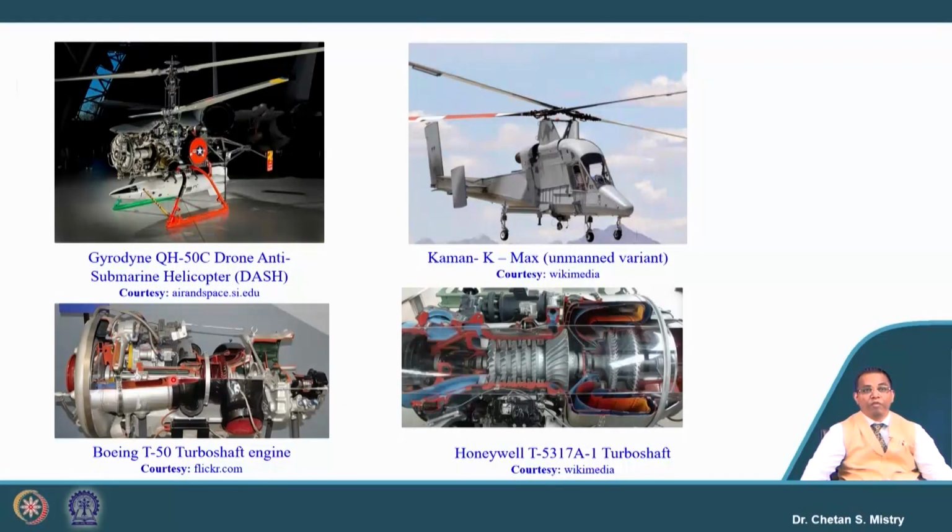If you recall, we have discussed a similar kind of engine even for the turboprop engine. So you will understand that a turboprop engine also can be used as a turboshaft engine. Yes, but you need to do certain modification, or maybe no modification. In a turboprop engine the thrust we are discussing is generated by the propeller as well as by the nozzle. Here in this case we are not bothering about the thrust.